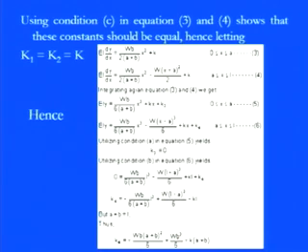In place of k1 we have k, and this equation, EI into dy by dx equal to WB by 2 into A plus B into x square plus k, is valid for the AB region. Now for the BC region, again for the slope condition, EI into dy by dx is equal to WB by 2 into A plus B into x square minus W into x minus A whole square divided by 2 plus k.